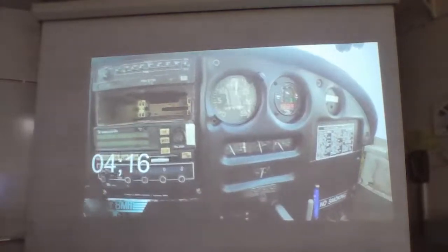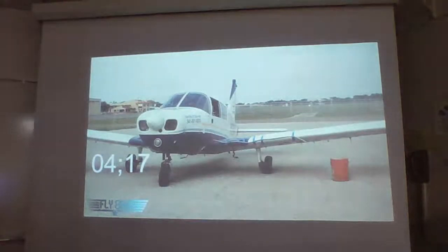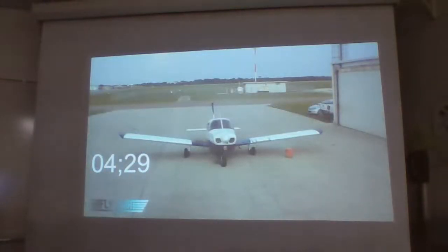Over 75% thrust. So if you guys take absolutely nothing else away from this video, at least remember this. Whatever you do, don't freak out. There's a couple different things here. A, our engine's running for a very long time. It's actually making enough power to not only maintain level flight, we could actually climb a little bit with the power that we were making. And we had several minutes of full power after losing oil pressure with nothing acting weird at all in the engine. Now, not to say this is going to happen to you.